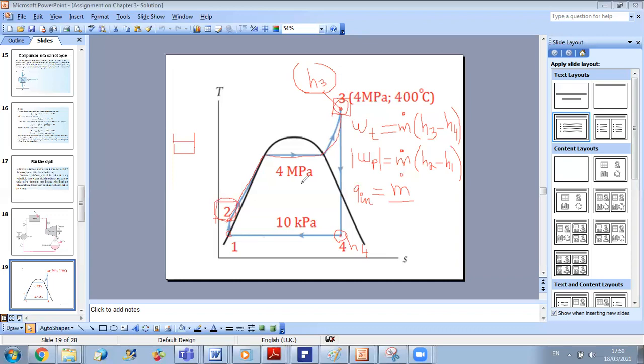If you went over the videos, we explained in detail that when you have a fluid moving, the variation of energy is m dot delta H. While if you have a closed system or a fluid at rest, then the variation in energy is m dot delta U. Okay, so don't confuse both here.